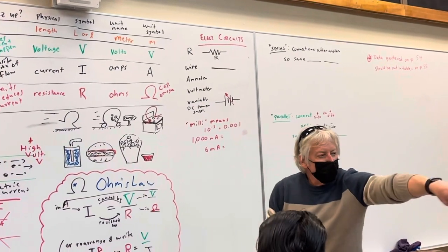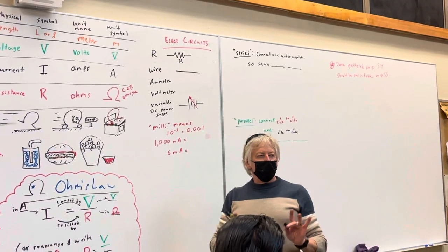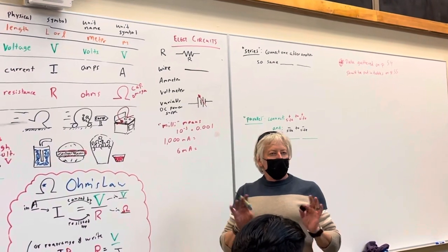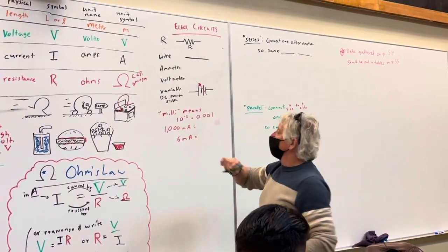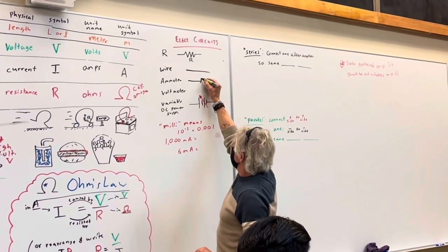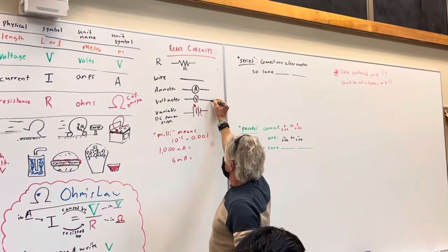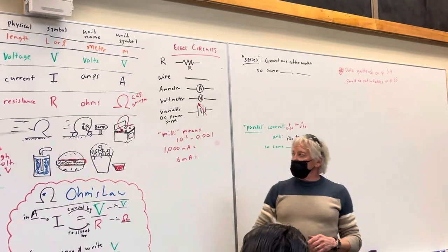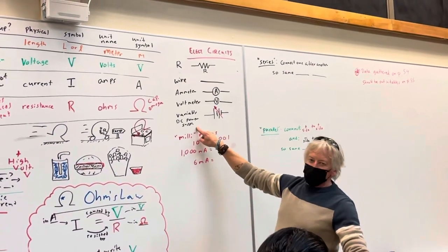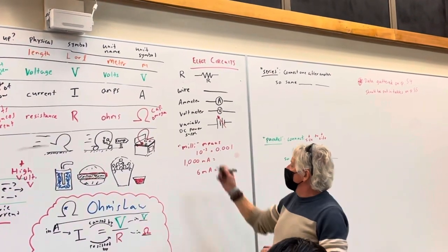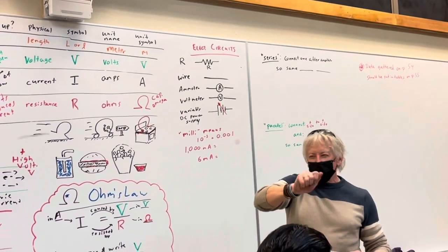You've got 2 yellow boxes there. They're called DMMs, digital multimeters, meaning you can measure all kinds of things: current, volts, resistance. An ammeter is drawn like that, and a voltmeter is drawn like that. This is on your front page, so you don't have to write this really. And a variable DC supply means you can adjust the voltage. That arrow means you can get more or less volts just by turning a knob.